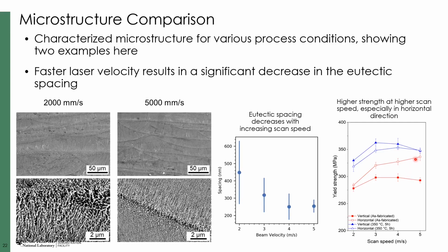You see that there are also some changes in the anisotropy here. That's an interesting detail that I'm not going to spend time going into here. We're working on a manuscript that details this. You can also see that we get a pretty nice hardening response during heat treatment, as well as some variations in the amount of anisotropy in those properties. But I want to focus on this here, where we're seeing that our strength is clearly a function of these processing conditions.